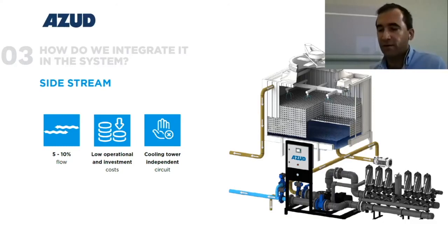And finally, you have an improvement in your production process and a reduction in downtime. When a cooling system is fouled or has scale buildup, production may be slowed due to inefficient heat exchange equipment. In some cases, the cooling system and heat exchange equipment may need to be taken offline for repairs, decreasing your production.